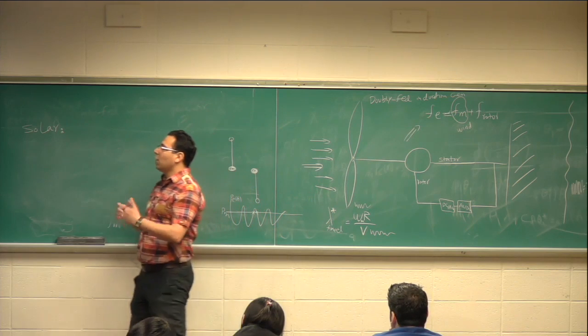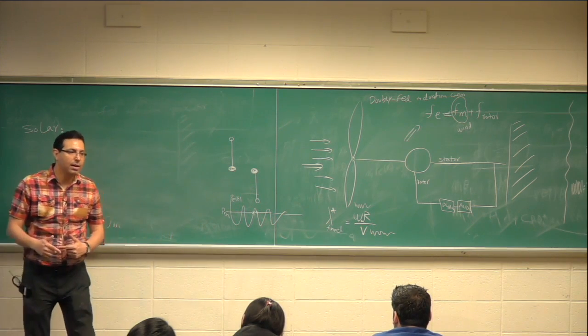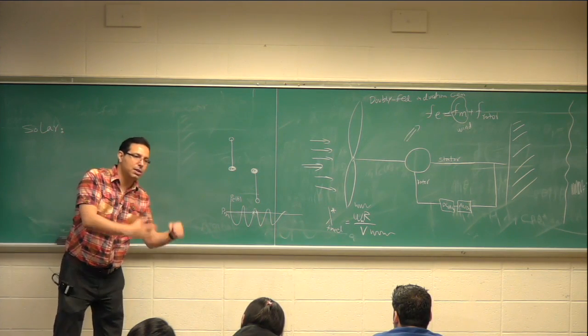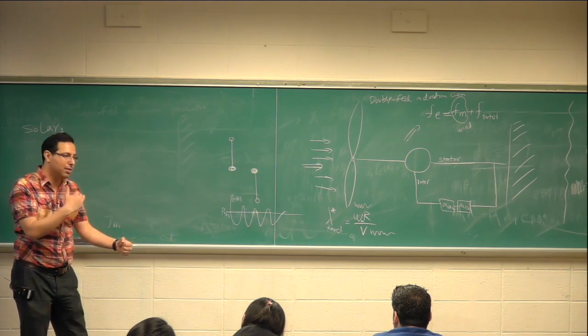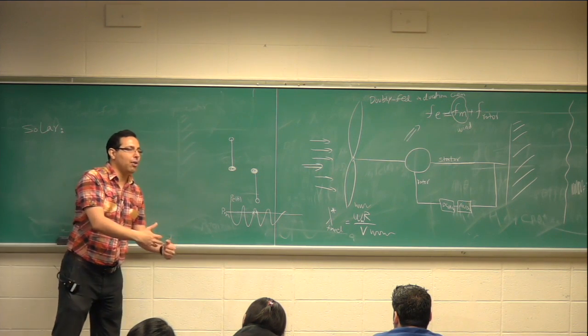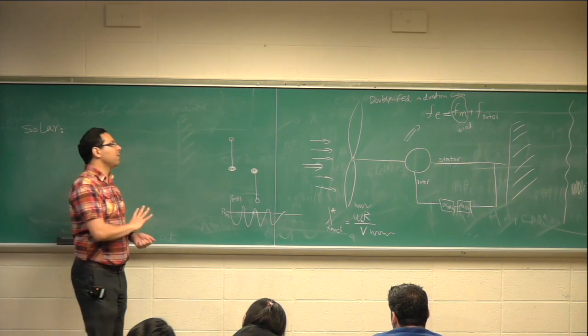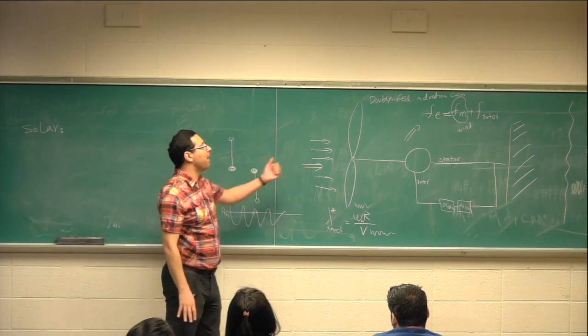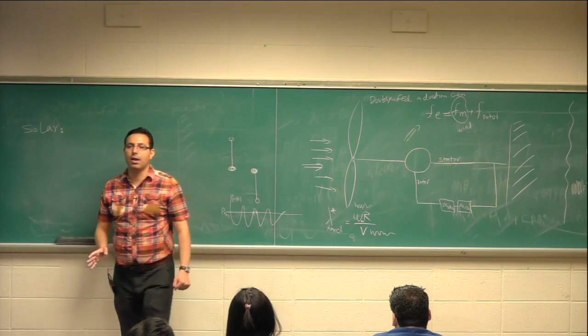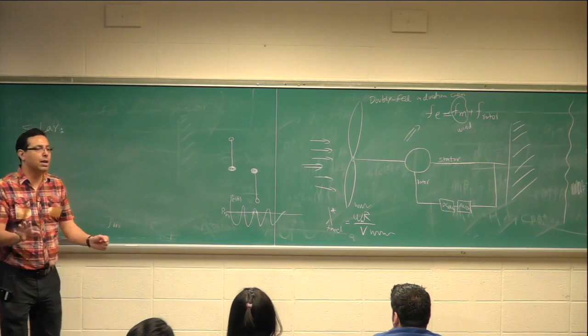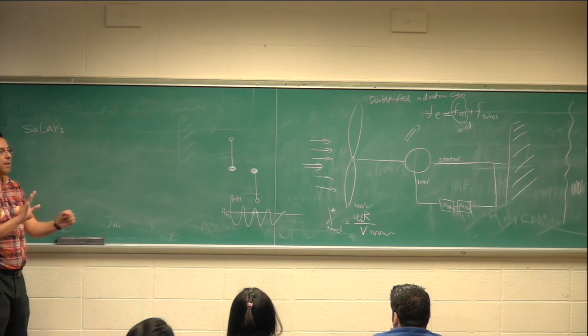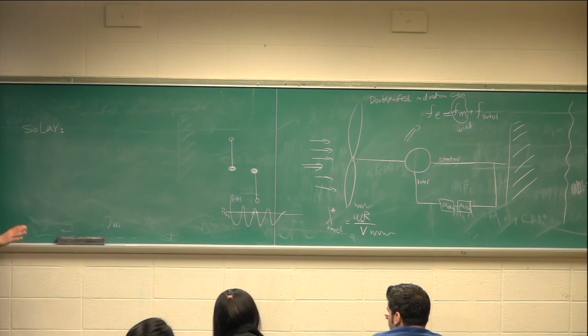In the world, if you see a blackout, it's just because there is a fault in the system, and a fault means disturbance, and the disturbance is outside of the region of attraction. So if there was a notion of global stability for power systems, there would be no blackout. Because global stability just deals with faults 100%, which is too good to be true.